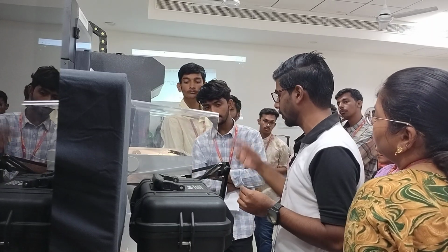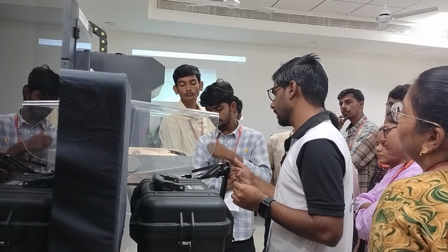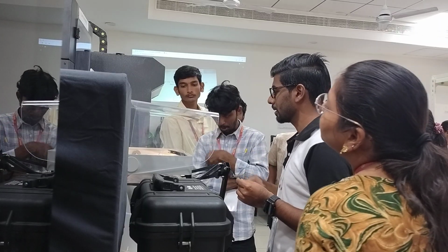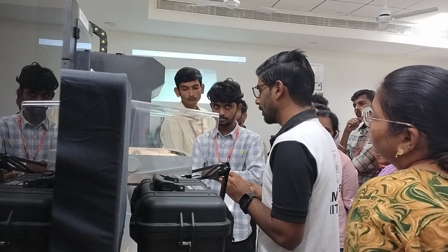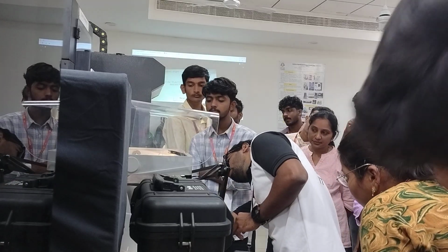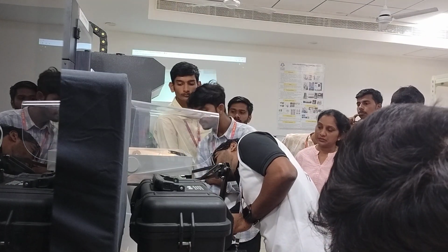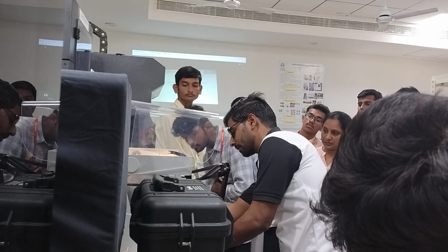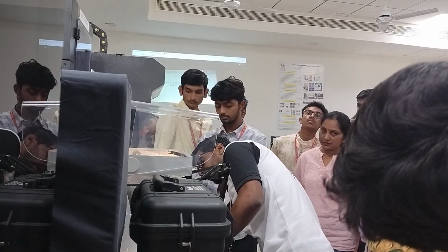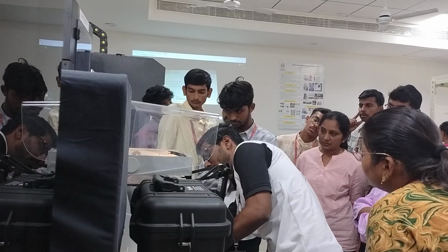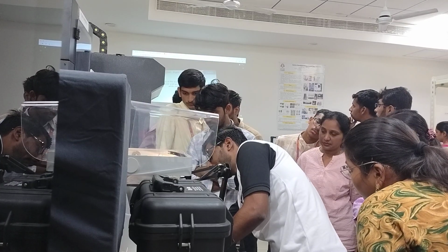As I showed you before, there are two nozzles. The front one is the fiber nozzle, the second one is the matrix or the plastic nozzle. So I have to place it between the plastic nozzle and my bed. I have placed it there, and then I click next. Adjust the thumb screw directly, okay?